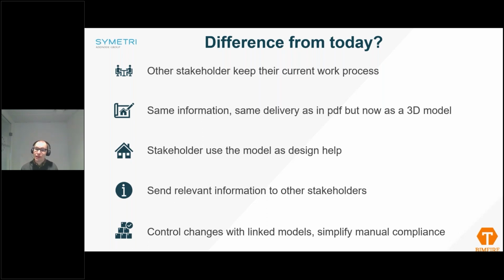But what I also like to mention is that both you and the fire engineers can start doing a simplified manual compliance. I usually say the most simple one, take a wall for instance. You can start checking the fire rating on that wall as required, and in later stages when you have an as-built, you can check that all those required walls are actually fulfilling those as-built.